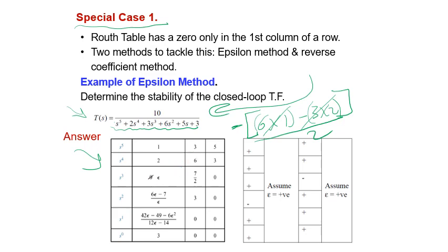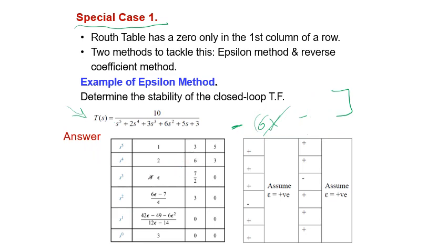And that's the problem. If I keep the 0, you are going to get the rest of the table as zeros or infinities. You cannot continue with the table. And remember, in this kind of calculation, I don't need the value. I need only the sign. For that, he's saying, let us replace this 0 by a certain value. That value is considered a very small value, so it's going to be epsilon.